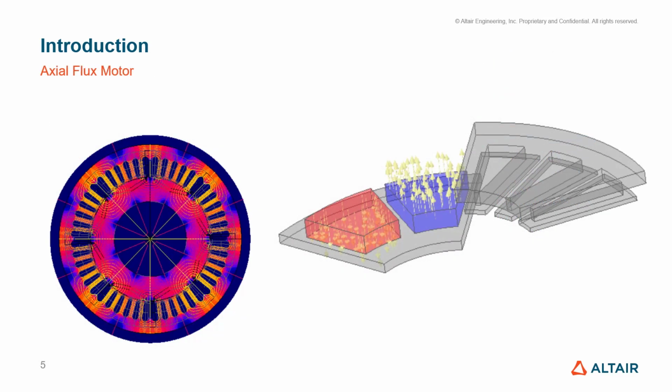In fact, while a radial motor in most cases can be computed in a 2D domain, since the magnetic induction that goes through the air gap can be considered constant along the path length, in the axial flux machine case this is not true, and we need the 3D domain to properly compute the flux lines and so the magnetic field distribution.